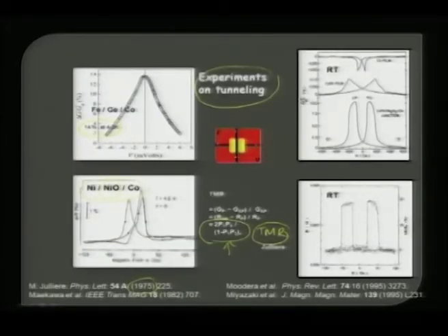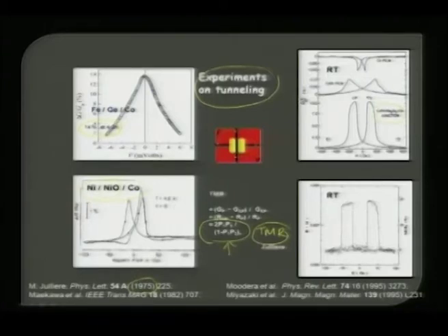You can also get a very nice TMR response if you have a permalloy alumina cobalt junction, where alumina is used as a tunneling barrier because alumina is a very good insulator. So, it is possible to get TMR devices like that, and this is another example where you can clearly see a very nice saturation for a spin valve junction operating on a TMR property. You can get this sort of response if you try a variety of tri-layer or bi-layer devices.